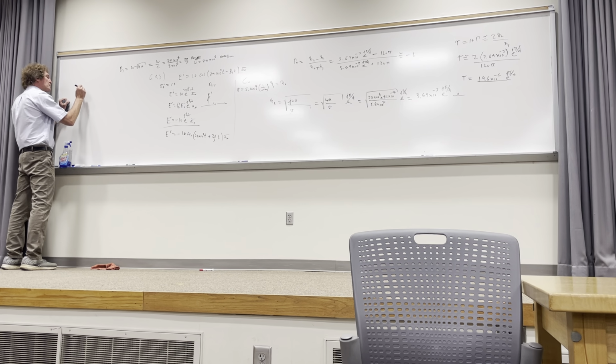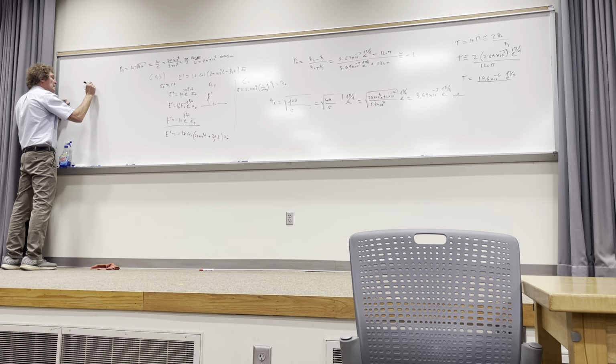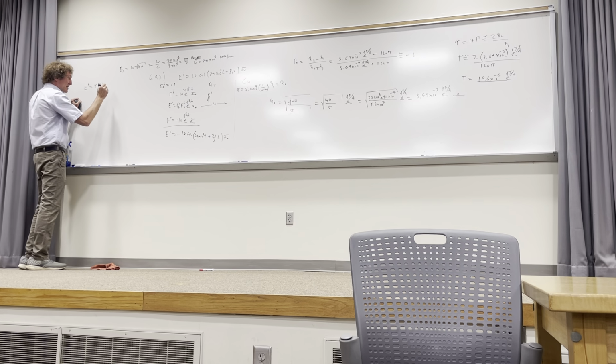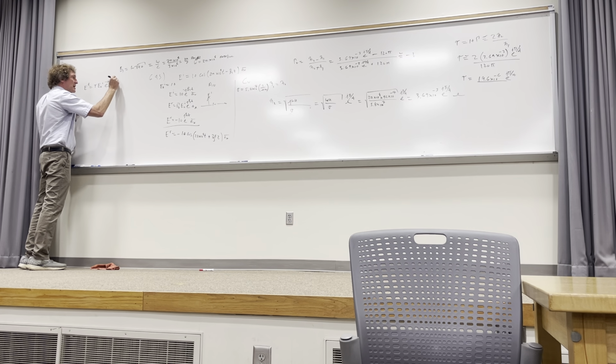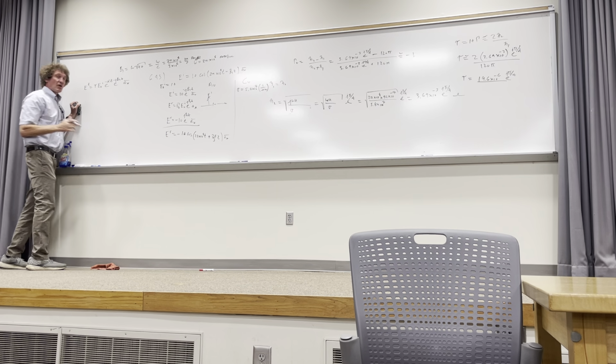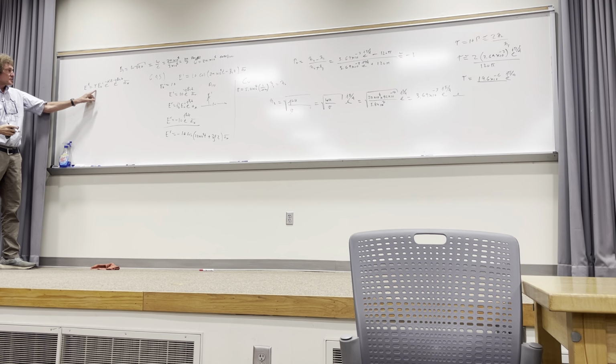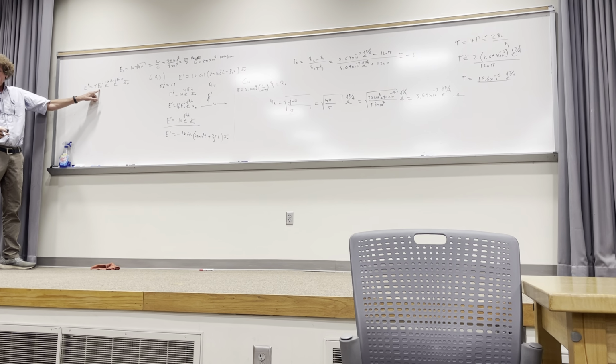If you want the phasor form of it, it would be what? E transmitted would be the transmission coefficient times E naught incident, and then it would be times e to the minus alpha z, e to the minus j beta z, in the a_x direction. Do you all follow me on that? Transmission coefficient times E naught incident is the magnitude of the transmitted electric field, right?